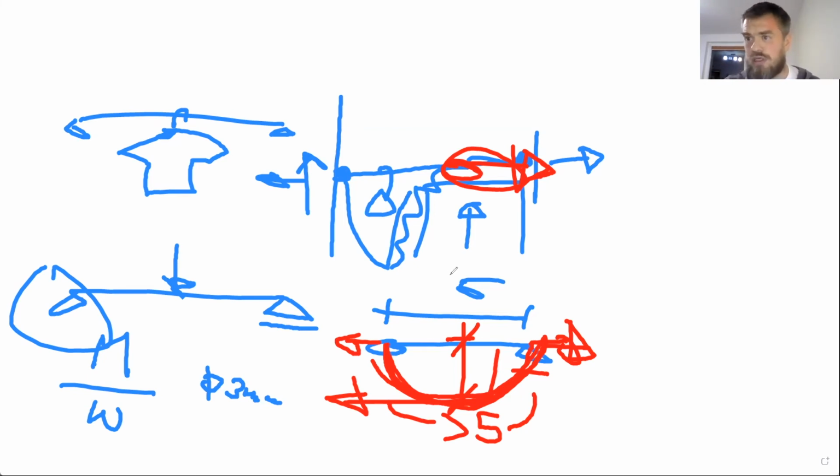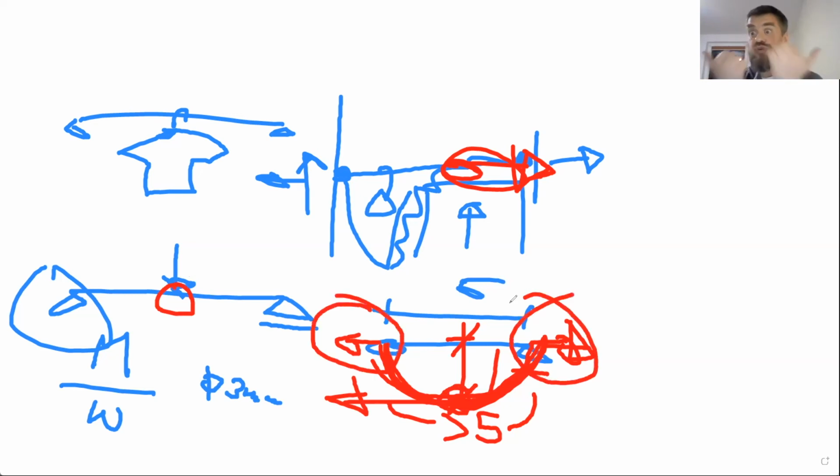But what I have to also add is that you don't really want to think that nonlinear geometry is good. It's neither good nor bad. Sure, the string gets it better because the stresses in the string, compared to if the string was a rigid beam and a membrane state element, the stresses here would be like 1,000,000 times higher. But the supports in this schematic get a huge horizontal force they have to deal with. It's not for free. Something will get it better, something will get it worse.